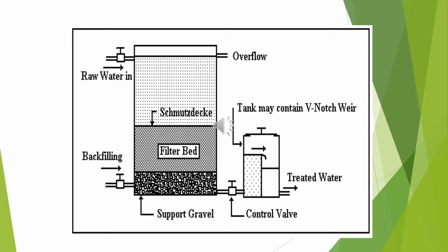And secondly, it provides a waiting time of some hours, that is round about 3 to 4 hours or even 12 hours, depending upon the filtration velocity, for the raw water to undergo partial purification by sedimentation, oxidation, and particle agglomeration. Now the level of the supernatant water is always kept constant. Then there is a layer of sand bed.